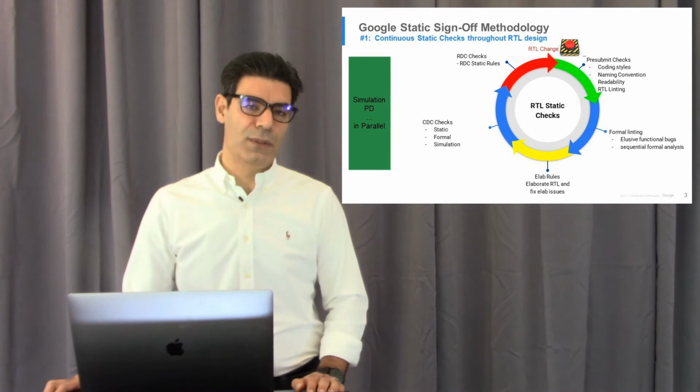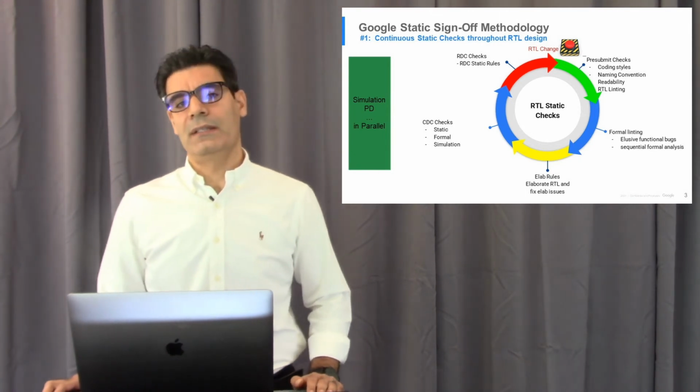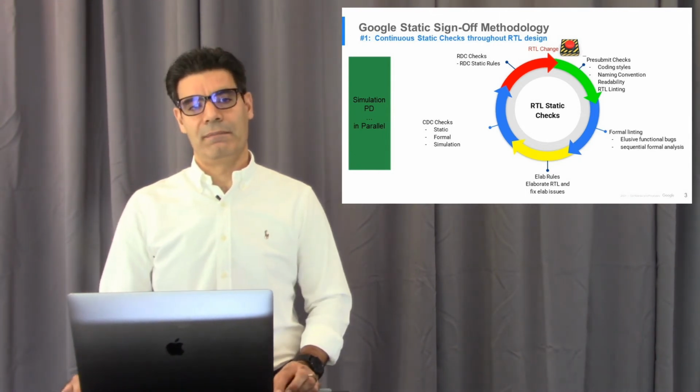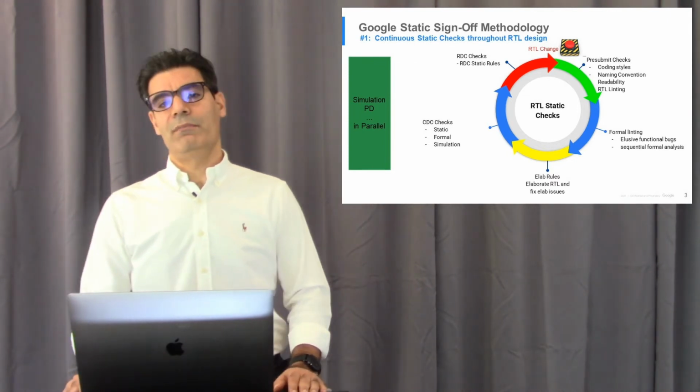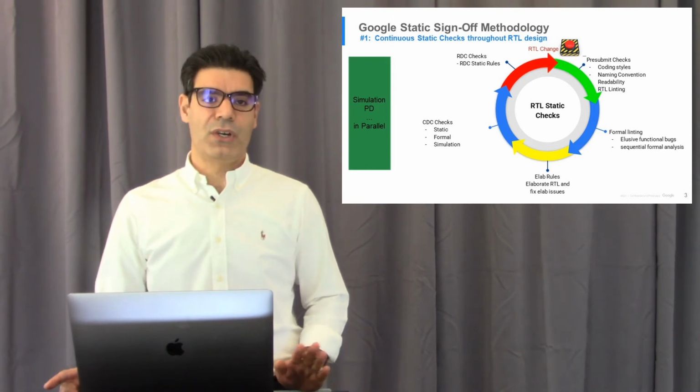Imagine you wait for the entire RTL to get ready and verified before you do CDC verification. At that time, the CDC reports will be huge, and the noise number is too high and makes it much harder for you to close.